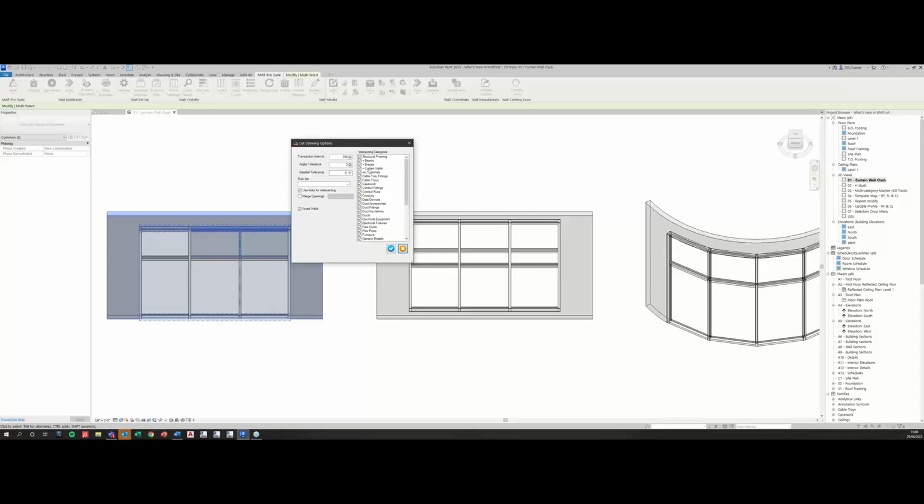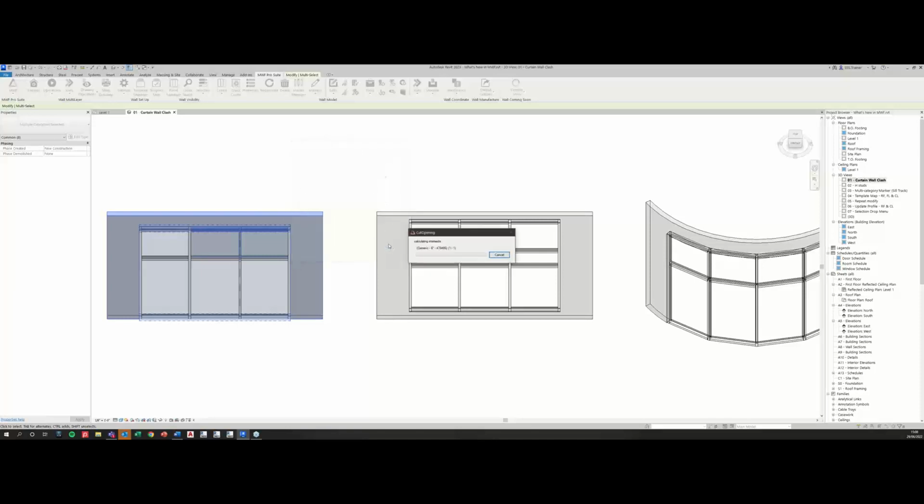Okay. So when running an interference, we can select the elements that we want to clash against, and those are on the list on the right hand side, as you can see here. And we can just uncheck the ones that we don't want to run in the clash, but we can then just select the ones we want to include in the clash. Here I'm just going to leave these all selected. I know I've got a wall panel and my curtain walls, so I know it's going to clash these two at least anyway. Okay, so I'm not going to run arced walls. I can run this on intersecting on a linked model as well, if I had a linked model. But anyway, for now, what I'm going to do is I'm just going to run the clash.